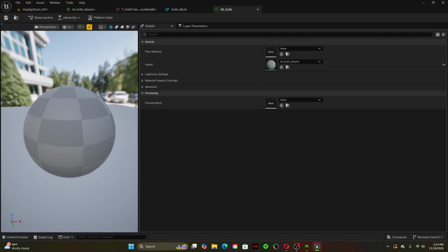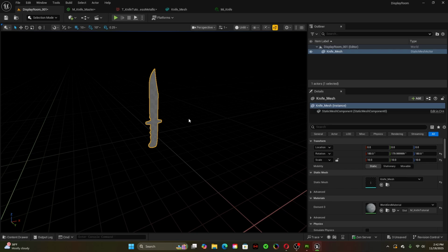So why did we make an instance? An instance is a cheaper rendered version of a material. A good and well-organized game is going to use material instances for specific things. It's going to make a master material, and then the material instances are going to be the same material, but plugged in with different textures and different parameter settings, pretty much for free.